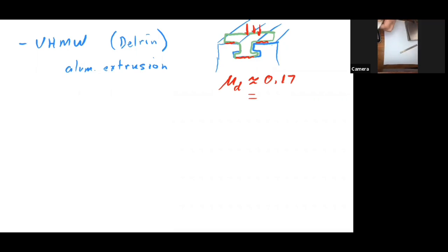If you did put load on it, either some sort of dynamic or moment load, then you really started to have it dig into the corners. And you also had one other problem with the sliding friction, which was binding.